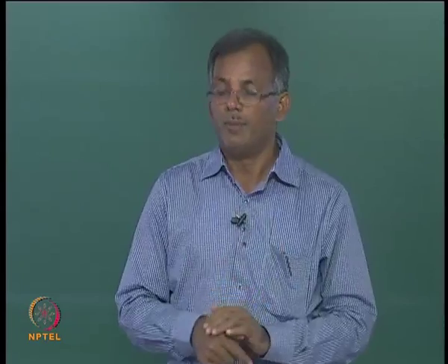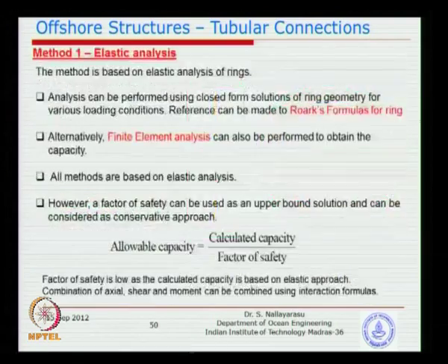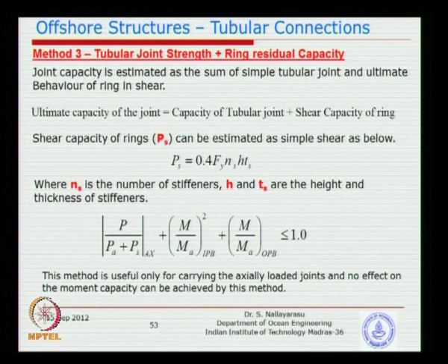definitely when you apply an in-plane moment, one of the stiffeners is going to get compression, the other brace is going to get tension, compensating. For sure it is going to help, but imagine if you have only one stiffener at the middle, yes, it does not have any moment capacity. If you put three stiffeners, for sure it is going to be effective. The central one will take more axial load and the two outer ones will get the moment load. So that is one of the weaknesses that we find, and sometimes people do not agree, especially the contractors.